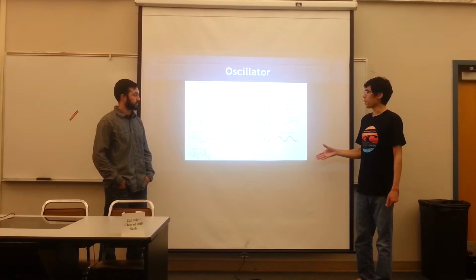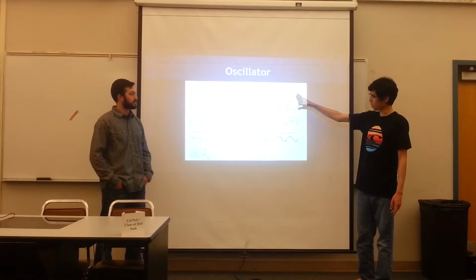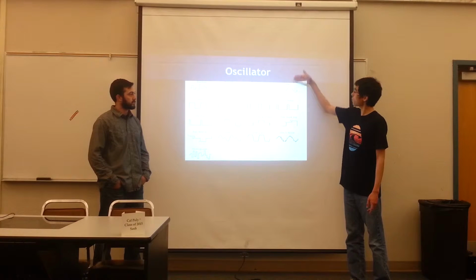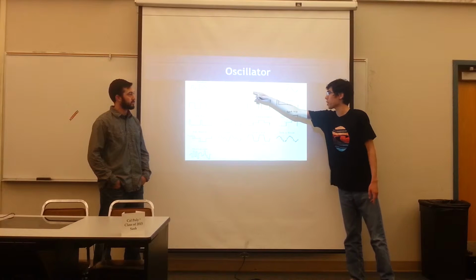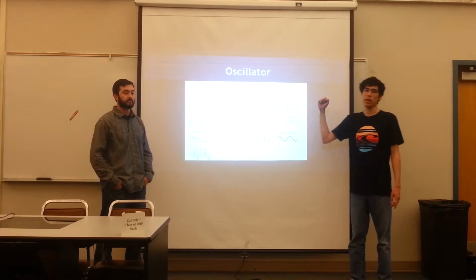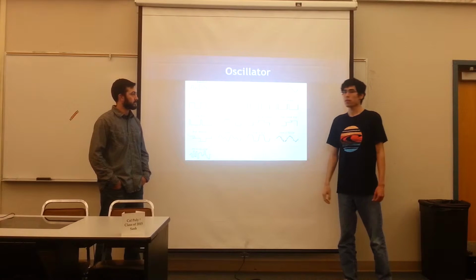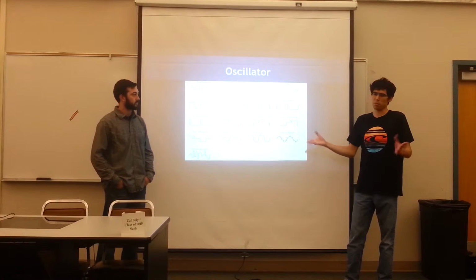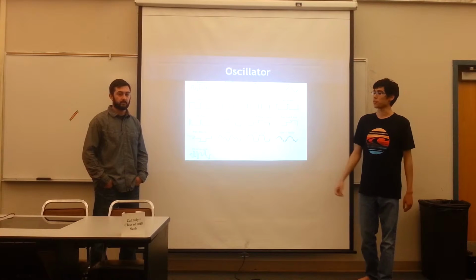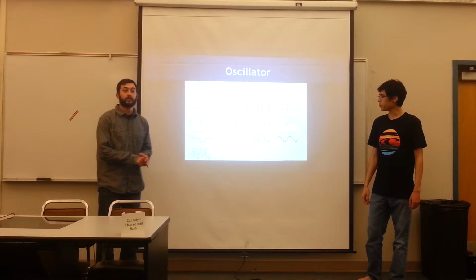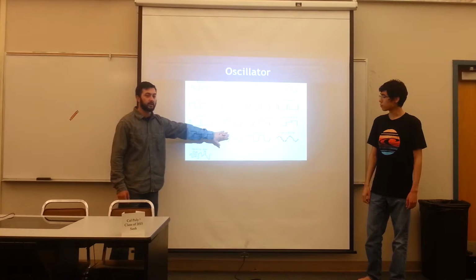And what we do is that we have several different counters for each of our signals, and we add each of these signals together. For example, if I want to add a saw and a sine together, I just take voltage here, add them together, divide it by 2, and that creates a combined voltage here. That is then spit out to our output, which is just a simple LM Class D audio amplifier and into a speaker, creating our wonderful sound. And as we'll see later in our demo as well, once we start mixing these waveforms together, we get some pretty neat and interesting ones.